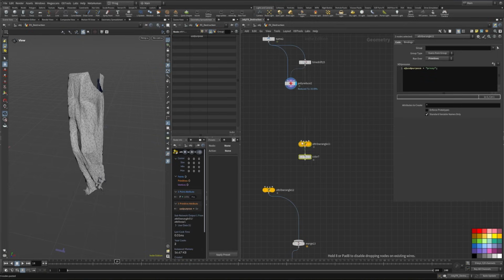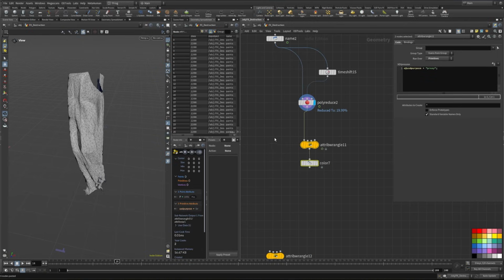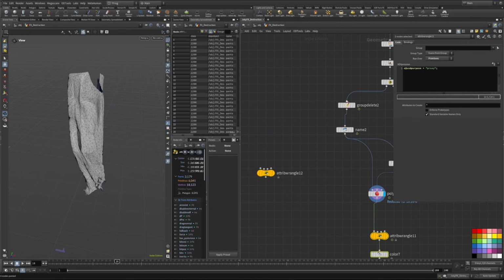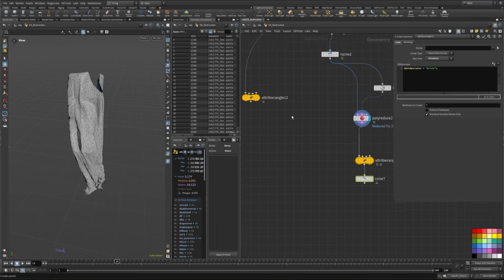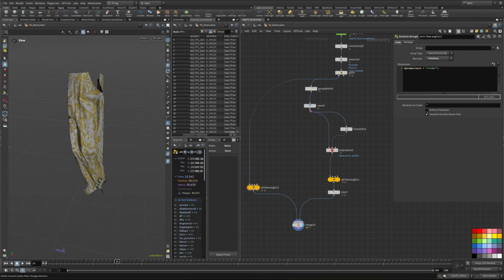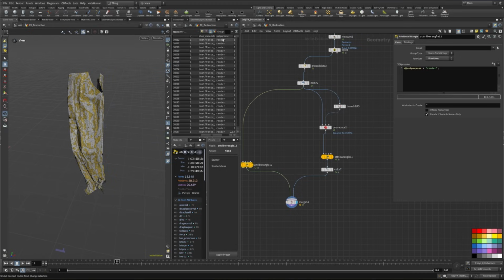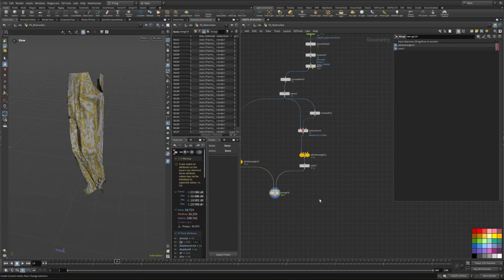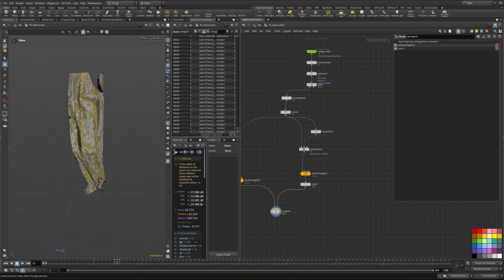So at first I want to use my proxy, plug this in here. And I also need my render geo, and I will plug this in here. Now we can merge it together. And you will see now that we got the name, because we need to plug the name into the render USD purpose. So we got our name and our USD purpose here. Great. Now let's move on and do the same for the strands.